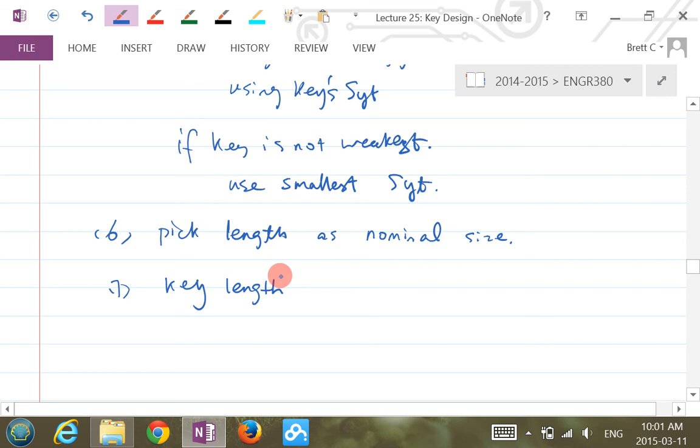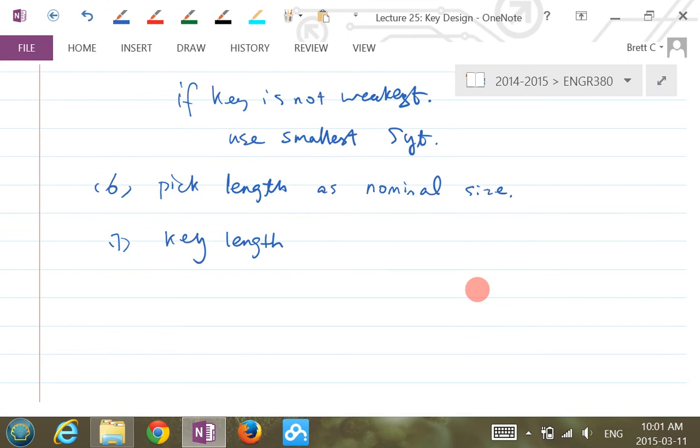It shouldn't be something like 1.5 diameters, but it should cover a substantial portion of the hub. In our design projects in the past, I noticed the key lengths turned out not to need to be very long. That gives you some freedom in terms of the shaft length and also the face width of the gear.